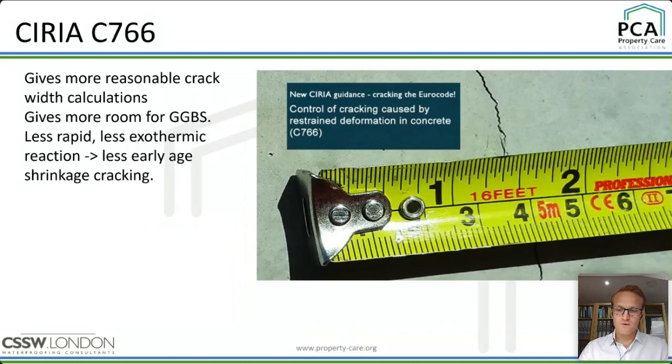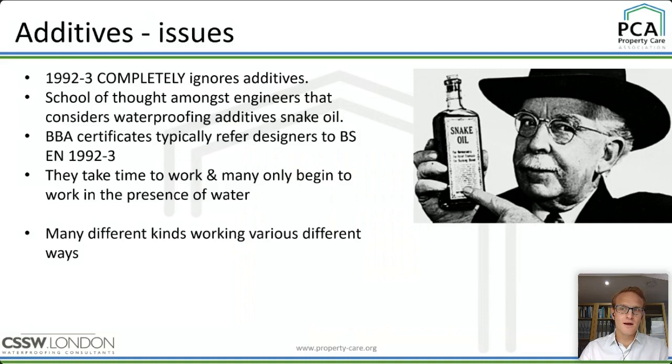Helpful document for structural engineers who are looking at crack width. But what about additives? We haven't mentioned additives at all. What about waterproofing additives? Well, Eurocode 2 Part 3 completely ignores any additives. It simply talks about getting your crack width down low enough.